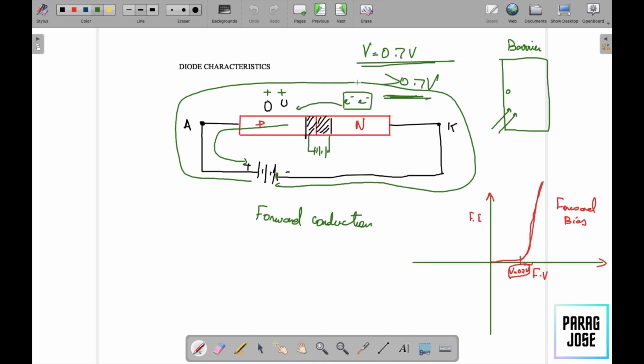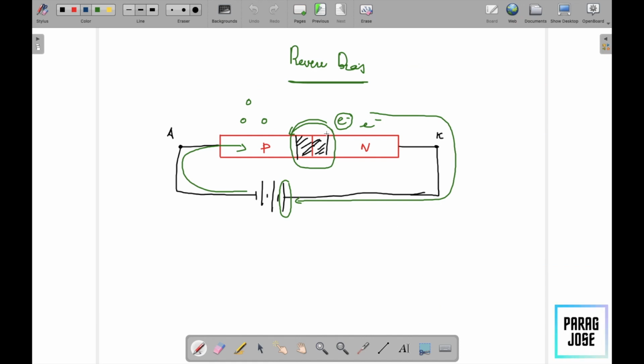So when we look at the characteristic of this, we can see that the characteristic will be something like this, where we have the conduction happening very slowly and then it suddenly shoots off. This shoot off happens because of a phenomenon called as breakdown operation, or this voltage will be known as breakdown voltage, VB. So this is basically the point where, due to this kind of motion of electrons, the depletion layer breaks down and therefore after that there will be free conduction of electron.